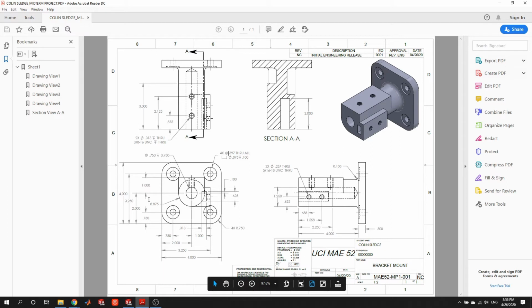So the next feature I like to add on the part is this cylindrical extrusion. So looking at this, we see that it's only called out here as a radius because this edge is only a partial arc of the circle. So we're going to have to double this to create the diameter of the circle. It's located in the center of the base, which we can snap to the origin in this case, the way we've dimensioned the base. And then we see from this view that from the face of the base, this face right here is extruded out 4 inches.